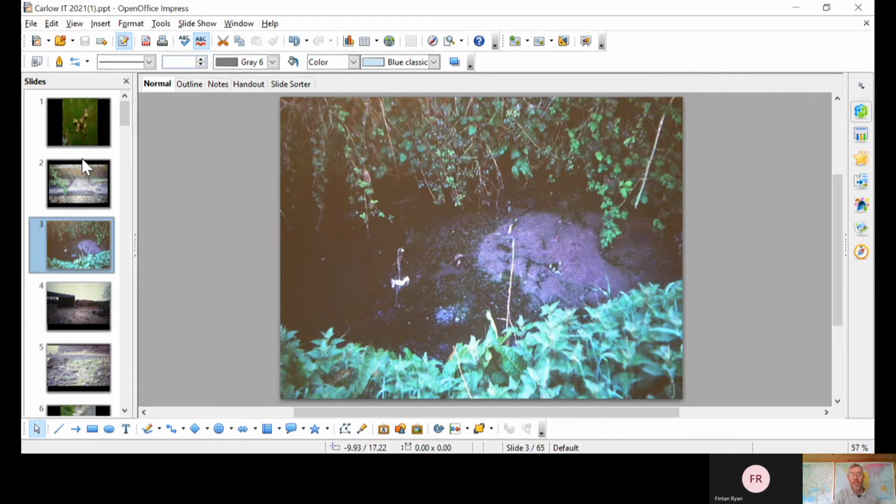So essentially what you can see here, the suspended solids loads obviously are through the roof. And the most immediate problem with suspended solids is simply just clogging up spawning beds, making it difficult for fish to see food, and just reducing the overall habitat value within the stream. So that's a very important one. But ancillary to that then, you can see the slightly greenish colour of the algae. So that green would be the result of nitrate and phosphate enrichment. And then when you get warm weather and sunshine coming in, the algae will grow and generally it's a sign of eutrophication, nutrient enrichment within the water. So there are a number of issues.